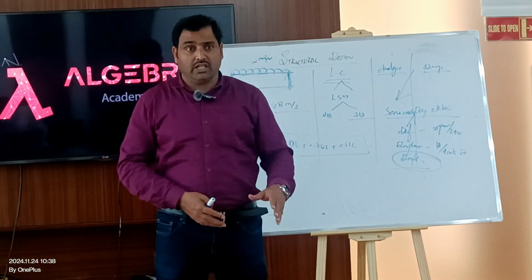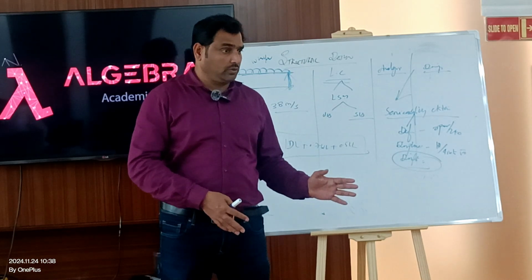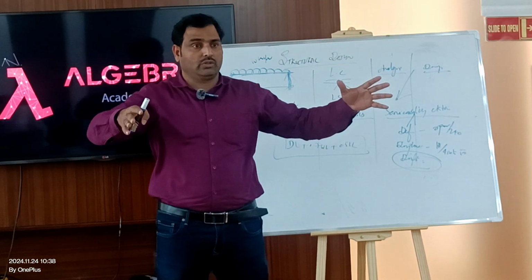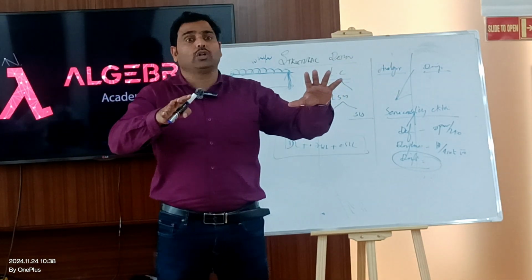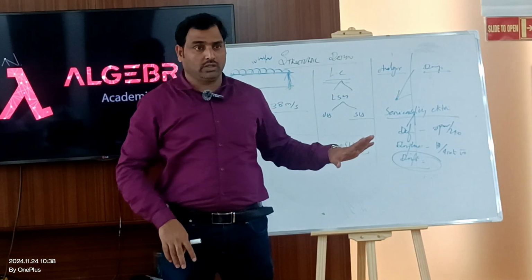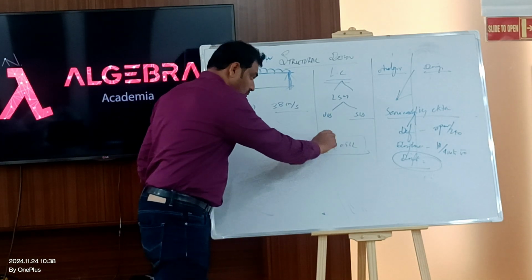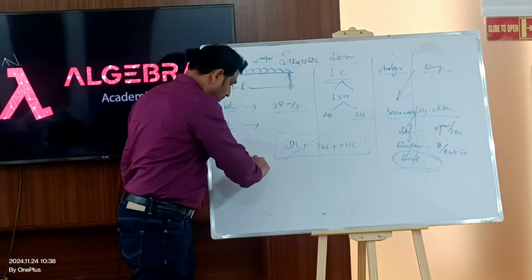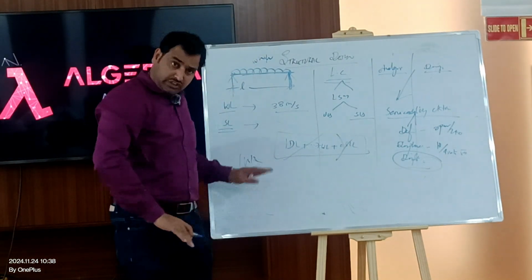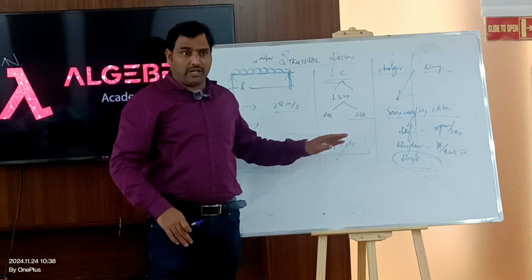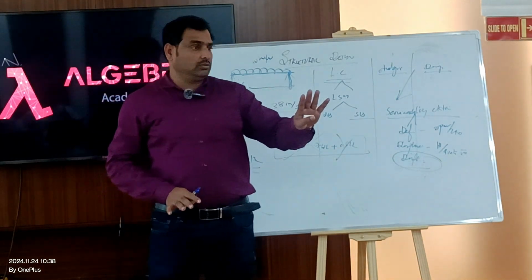In reality, the staircase is empty only. Correct? When there is a fire only, they are going to use it. So most of the places, what you have assumed as per code, is not going to exist in a realistic case. That is the reason the code is giving the privilege. But still, if you don't want to do this, if you consider 100% dead load by omitting the live load, still it will be safe. So what I am trying to say, it is very rare for a building to fail under wind.